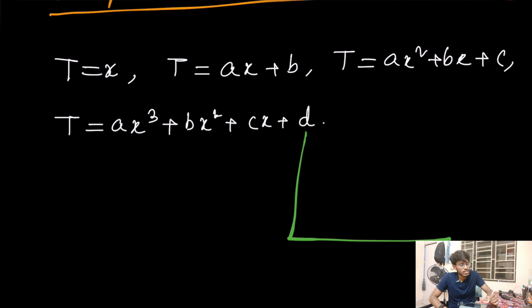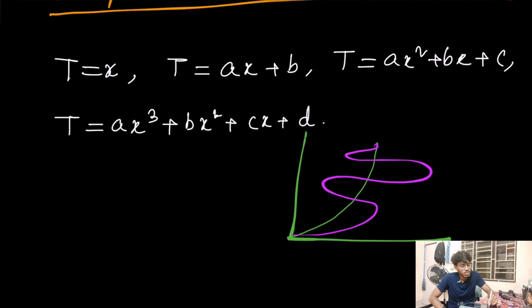In boundary layer theory, if this is the actual velocity profile and you take an assumption like this, you might say it is satisfying my boundary conditions here and here. No, this is not acceptable, my friend, because we physically know that there cannot be any backflow.